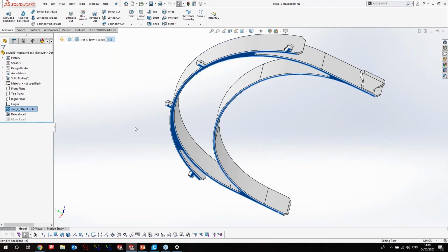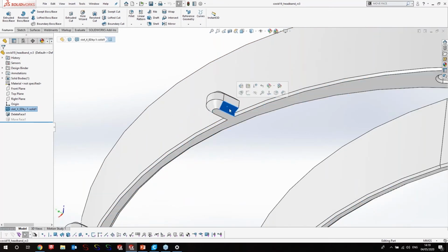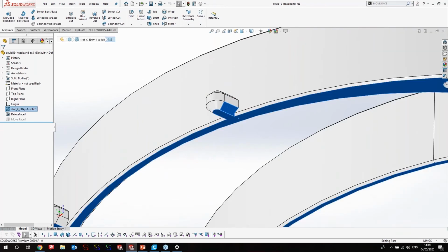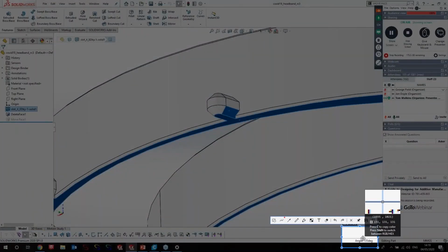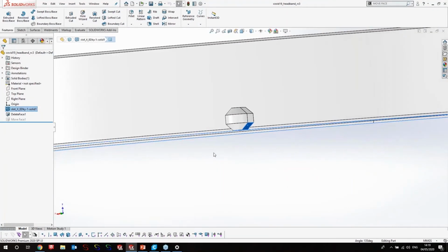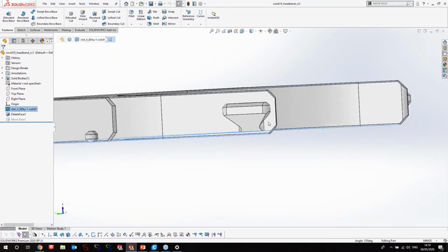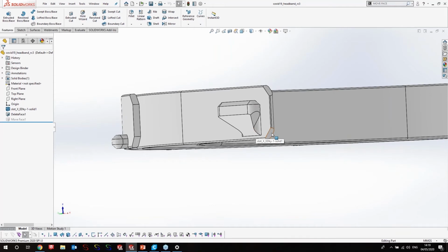So that's going to be the surface printed directly onto the build platform itself. We've got all these elements inside here. We're going to have the 45 degrees, or as we can see here, an angle of 135, obviously equaling the exact same. And we can spin the model around, you can see the same 45s in the back here. All of these sections, as I mentioned, are just helping to make sure that it doesn't require any further support material. So you'll also be able to see there are some chamfers at the back.